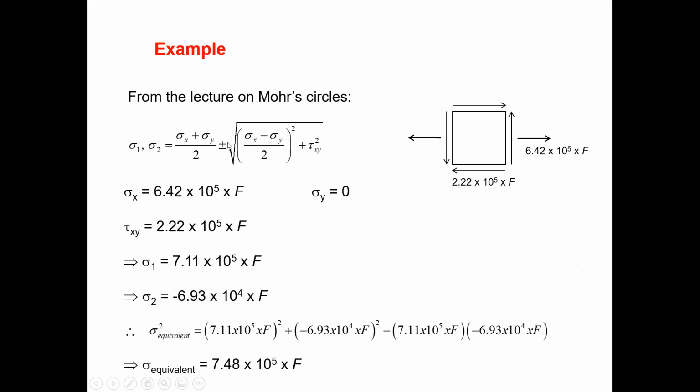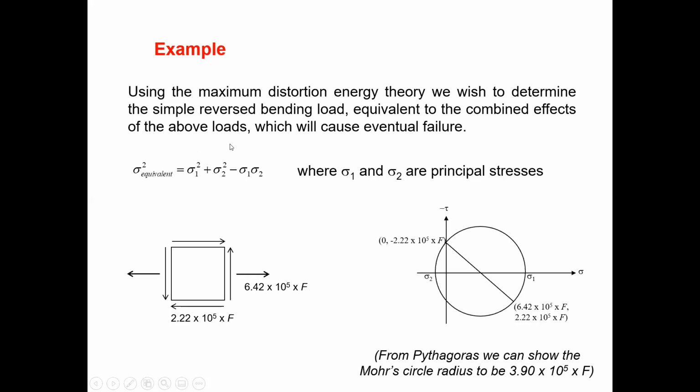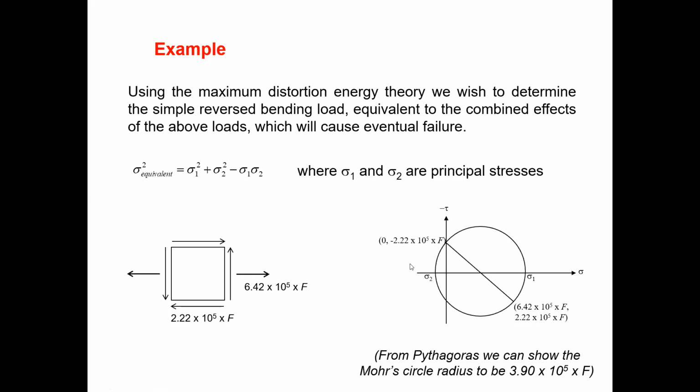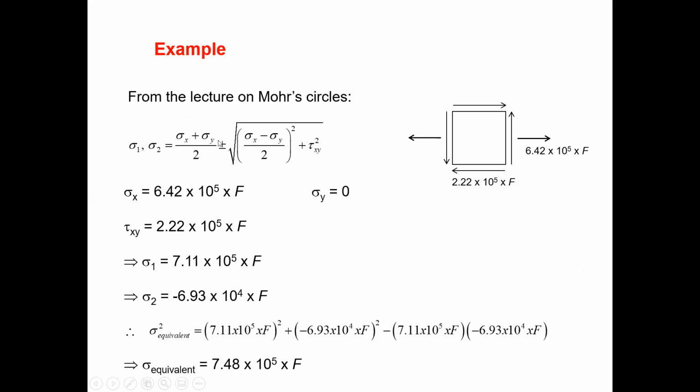You don't need to use more if you're not too familiar with the Mohr's circle theory, since they didn't tell you to use anything. If they mention using Mohr's circle theory, you need to find the equivalent stress, and definitely you need to use this technique. If they didn't ask, you can use the equation as well. So if you remember the equation for the maximum principal stresses, you can use this equation.